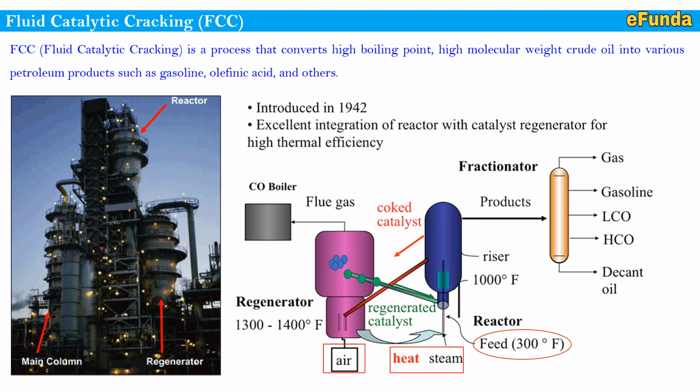Upon the heating the vapors are produced and fluidized, and the hydrocarbon vapors then pass to the stripping section where most of the volatile hydrocarbons are removed, and then it passes to the regenerator again.